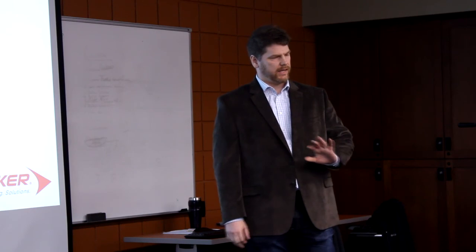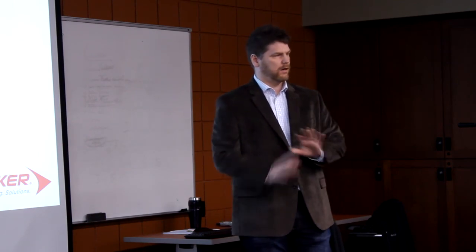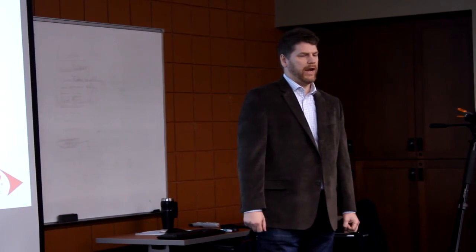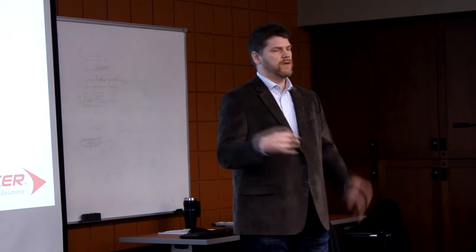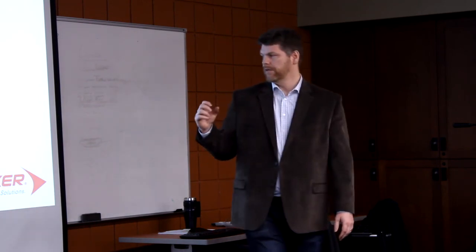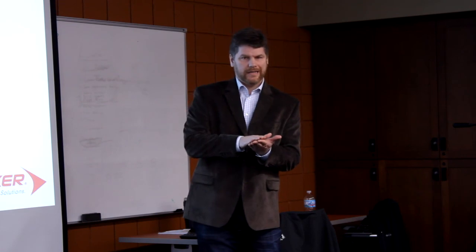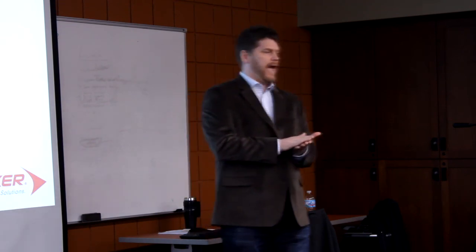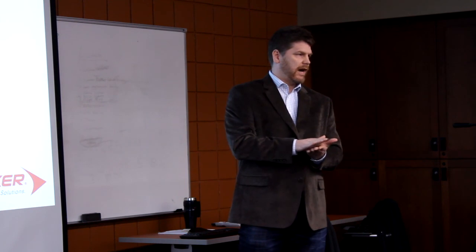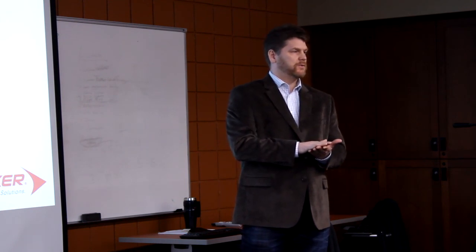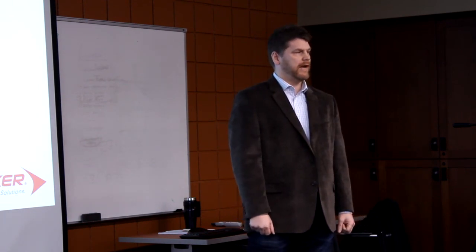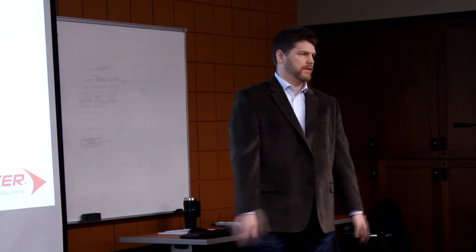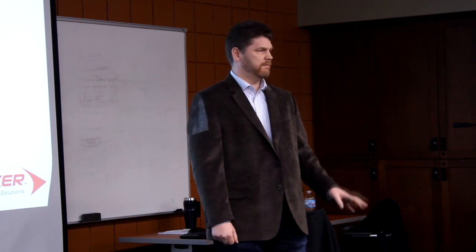Okay. So organic LEDs, or OLEDs, are a completely different animal. The way colors are made with the organic carbon compounds is not necessarily with different chemical lattice structures, but with the actual size and shape of the layering of the hydrocarbon layers. So that's a completely different animal. They can control that band gap, basically, in a different way, not with chemical means but by dimensional means, much like other electroluminescent materials that they've been playing with.